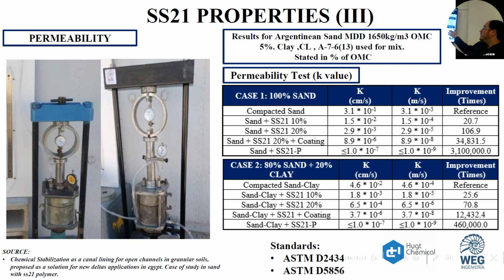So with that, we can see that with the use of the product and another variant of the product, we can get to semi-permeable and impermeable layers. That's what we are looking for when we talk about the geobarrier, and when we need to prevent the infiltration of water or any liquid we have in the landfill set. In this case, the liquid is much worse than water for sure, but when we need to get impermeabilization, we need these coefficient values.